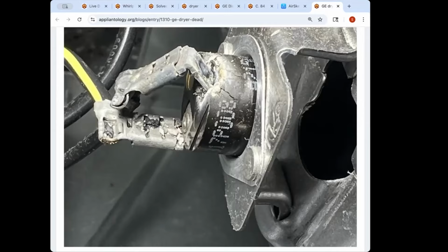Well, I actually think it's the combination of both the heat from the element as well as the amps going through. I think because that part brittles up over time, so between that getting dried out and the heat and the amount of amps going through there, it's just my observation that it could be both causing that.